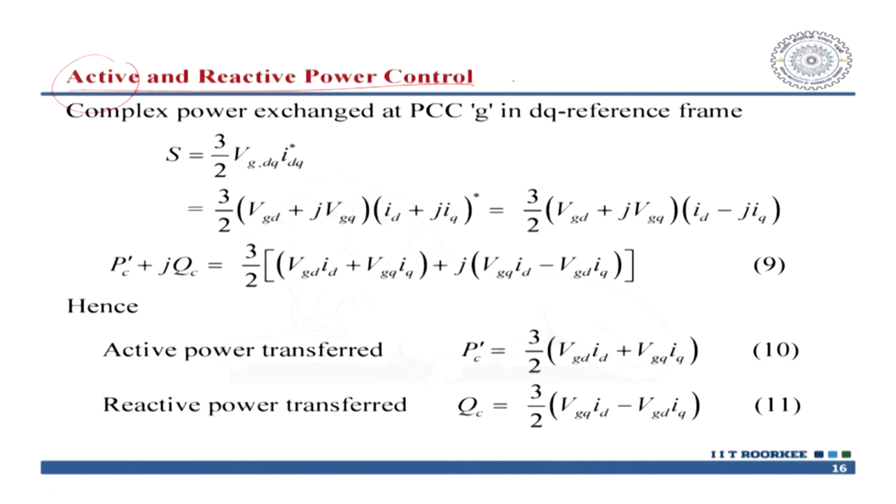For this reason we require to control the real power, as well as inject the power with certain power quality, because you are allowed to inject power at 0.95 power factor, you are not allowed to inject at any power factor, and for this reason we require to actively control the active and the reactive power.